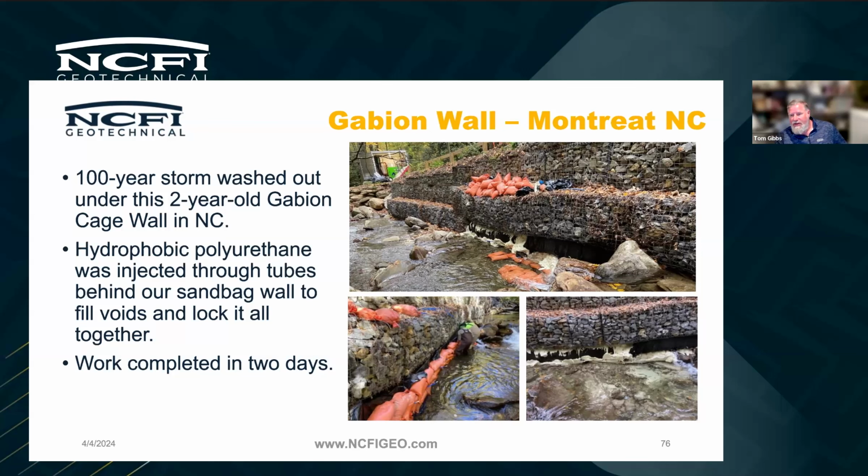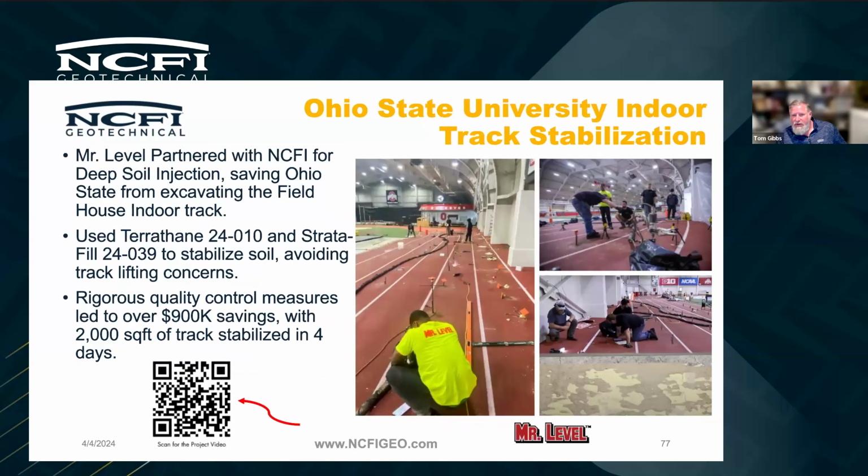So at the bottom, underneath the portion that's wrapped in geofabric, there was about an 18-inch tall and 3-foot deep scour up underneath there. So we put the sandbags in place and pushed the material through PEX tubing, and anything that came out was caught with a boom a little bit further down creek. You can't see it there, but any material that came out was caught there. So that helped with that project.